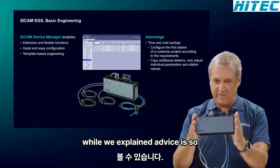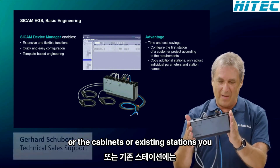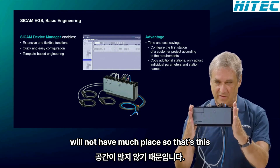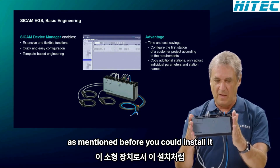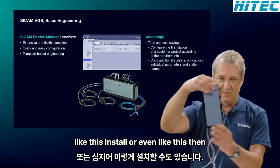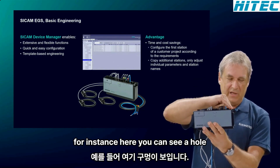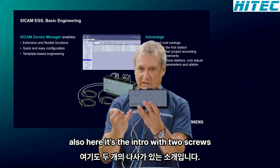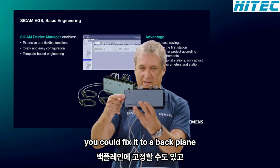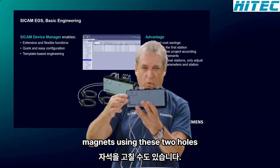Why did we explain this, why is it so important? Because in distribution panels or cabinets or existing stations, you will not have much place. So that's this compact device. As mentioned before, you could install it like this, or even like this. Then how to mount it? We already explained it. For instance, here you can see a hole, also here a second hole. By 2 screws, you could fix it to a backplane. Or you could even fix it by magnets using these 2 holes.